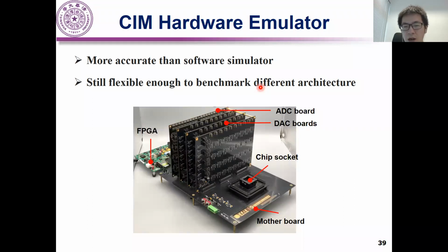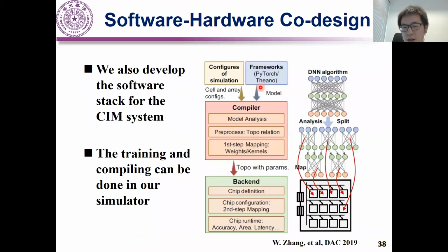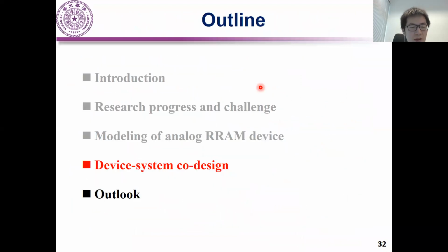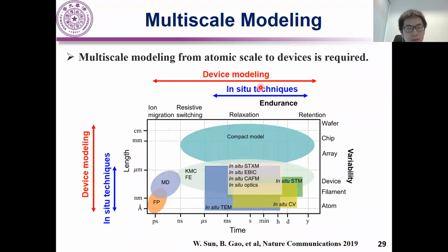For a large capacity memory, if you want to achieve a 10-year lifetime, for a single cell you need 4.8 times 10 to the 17 cycles of endurance, which is impossible for RRAM. What do you think we can do to solve this problem? In general, these two questions are about the accuracy of the modeling and the reliability of a single RRAM device. Can you address this too?